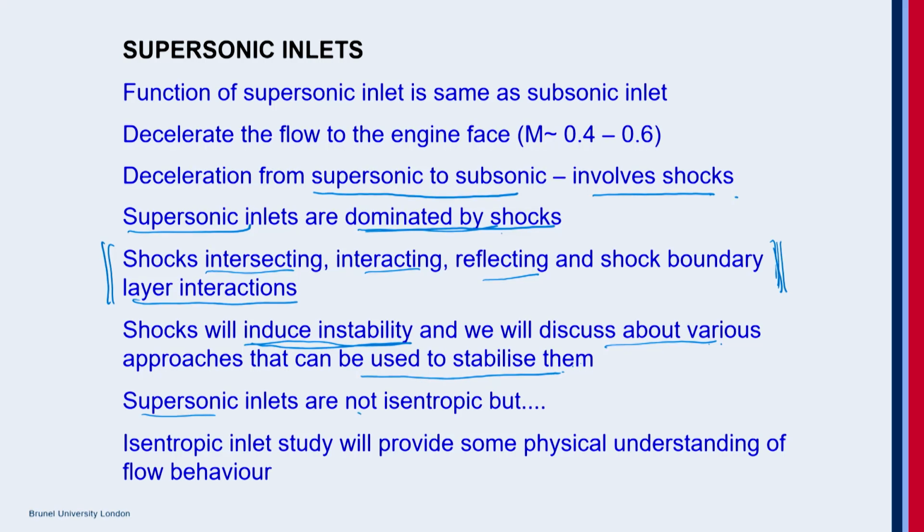Supersonic inlets are not isentropic because of the formation of shock waves. So you have to deal with the shock solutions. But nevertheless, we have to start with something much simpler. So we are going to look at the isentropic inlet study to provide some physical understanding of the flow behavior, and then we extend it to shock applications.